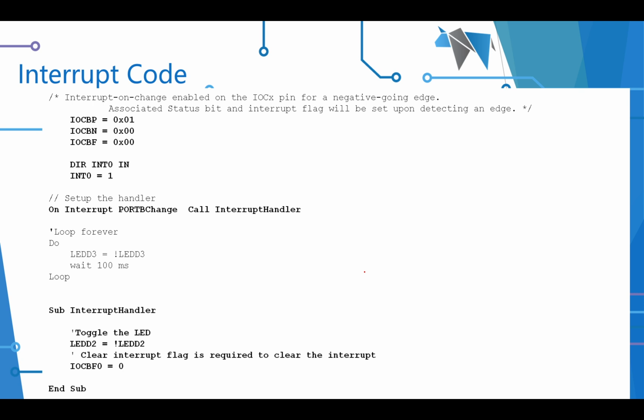Here's a cut of what we're going to go through. The interrupt is going to be enabled because that's automatic. And we're going to say we want to have it on an edge. That edge is going to be a positive edge because I've set that to 1. Negative edge is set to 0. It says negative here, but I might flip those over in the program. We'll see. And this is the flag. I have to set a flag. And a lot of this, unfortunately, you have to find in the data sheet. Hence, we don't know this stuff. Only you know that stuff.